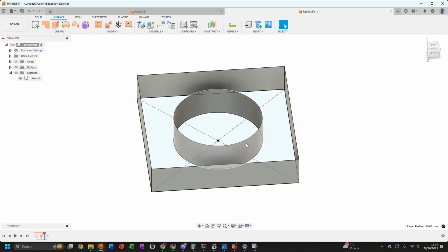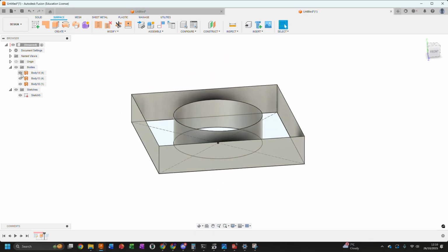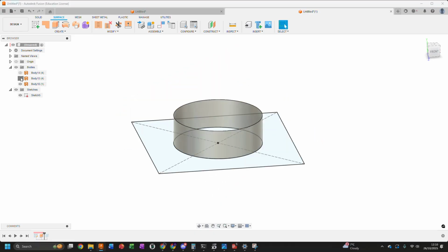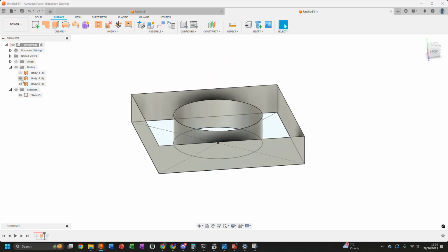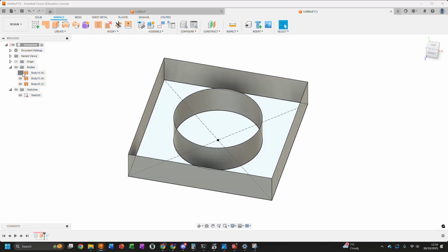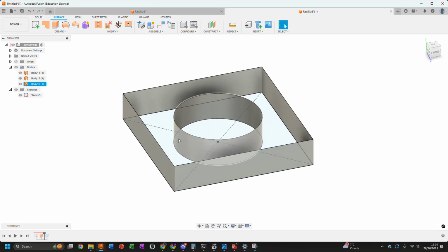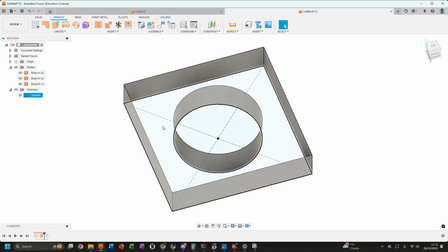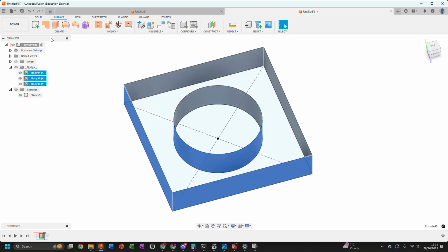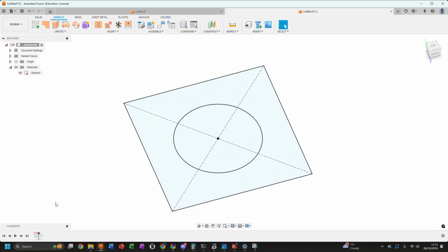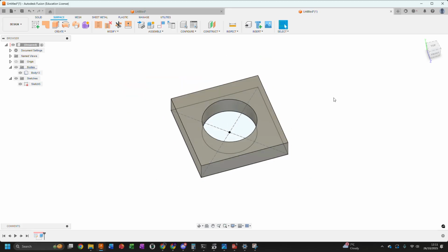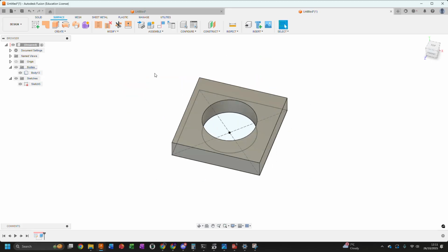It's created basically two surface bodies. It's created three. I'm not sure. Anyway, it doesn't really matter for the purposes of this video, but you can see it's created surface bodies. That's not really what we want. We want something with thickness for now. So we're not going to bother with the surface menu. Delete that over here, and now we've created our body like this.